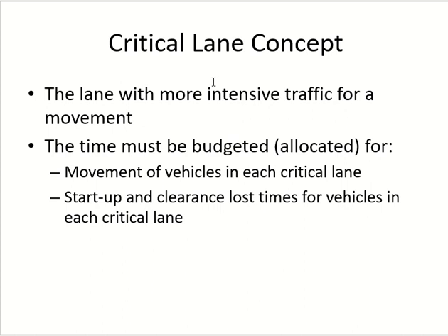Once you pick the critical lanes and take the volume, the signal time is according to the critical lane volumes. The green time is according to critical lane volume. The lost time, if you want to go and observe the lost time, again for critical lane. If you want to observe the headway, critical lane. Okay? Every phase has a critical lane and all the calculations are according to the critical lane. Okay?